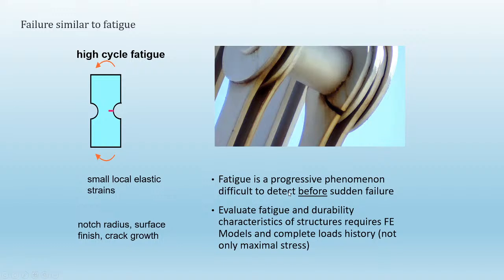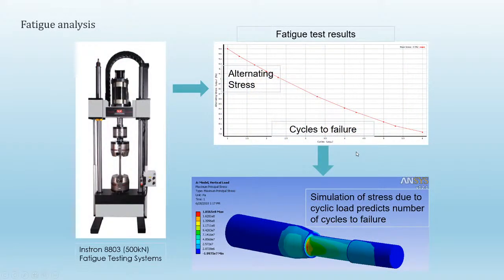It's oftentimes difficult to detect before sudden failure, and evaluation of fatigue and durability of structures requires FEA models and load histories of the structure. Since most of you are probably familiar with fatigue, I want to talk just a little bit about how fatigue analysis is done. We'll contrast that with how solder joint fatigue analysis is done.